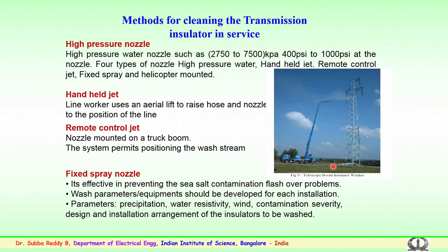The system generally permits positioning the wash system, so one could properly plan and clean the insulators in either tension or suspension type arrangements. Fixed spray nozzles are effective mainly in preventing sea salt contamination and flashover problems.